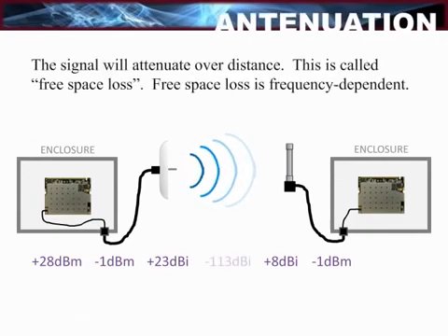The signal will attenuate over distance. This is comparable to the walls of a balloon getting thinner as it expands. This is called free space loss. Free space loss is frequency dependent. The higher the frequency, the greater the loss.